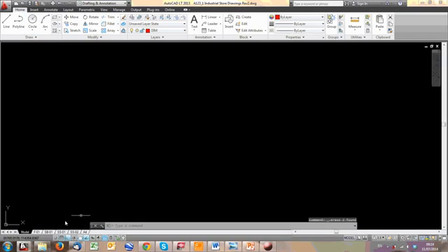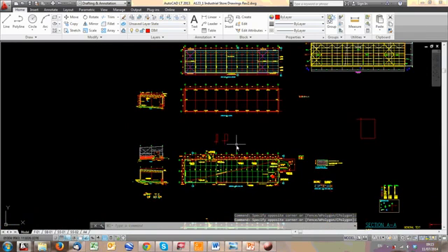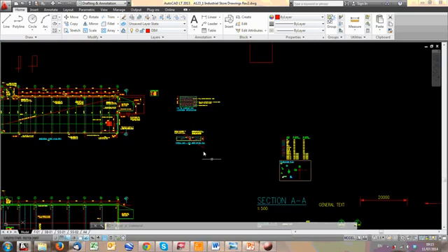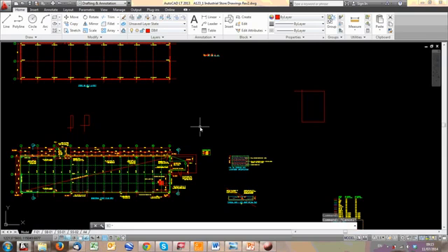We've covered the command line. Then at the bottom we've had a look at the model space, the paper space, and also there are various tools down the bottom here. Those are for scales, those are for tools. You can adjust scales when you're drafting. Be very careful of adjusting scales within model space. I'd encourage you, just for now, for simplicity, draw everything at 1 and 1, adjust your dimension tools, and just get along that way. You can, though, in model space, draw things at 1 in 100 next to a 1 in 1 next to a 1 in 50, and they will all come out looking as if you had produced it in paper space, but just be very careful of that.